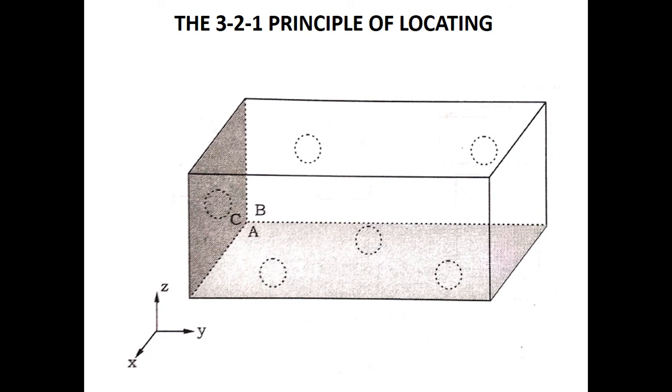Now let's define the degrees of freedom. Some of the degrees of freedom are arrested. With reference to this figure, the linear movement along the negative z direction is restricted, because I cannot push the block down, isn't it? That movement is restricted.